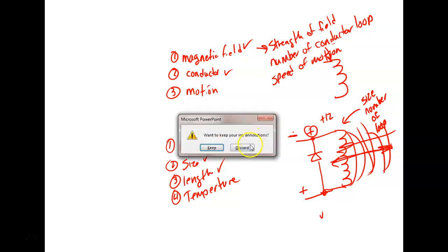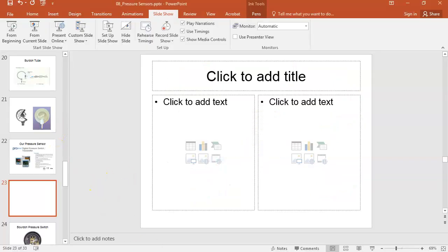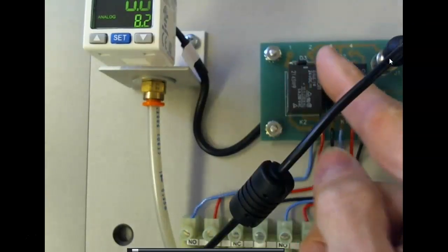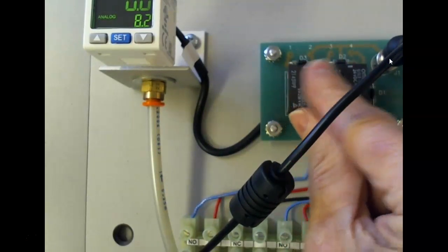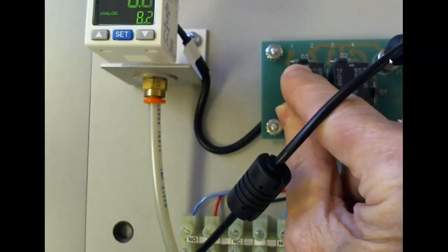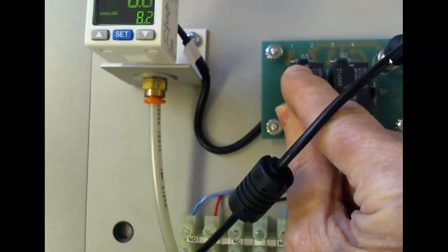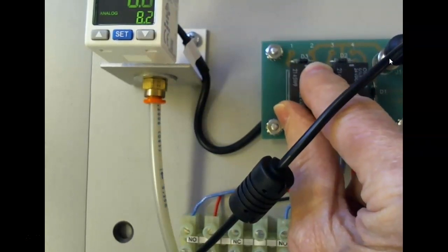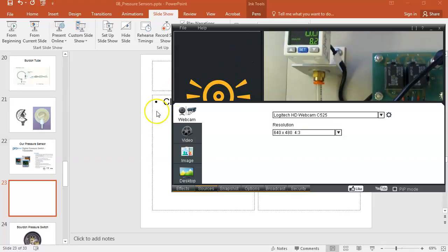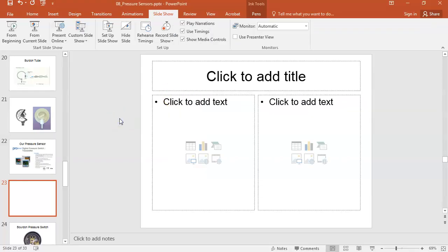So these are the counter EMF diodes there. Any solenoid that's operated off electronic devices, you'll see these guys right here. Can y'all see them? One end's white, that would be the negative side, and then this would be the positive side. If y'all go over and look at the Amatrol lines, when we go over there and let y'all try to find all these sensors, every one of these relays and coils, you'll see a diode across it.